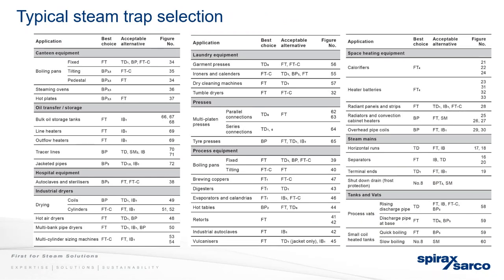There are a few things to consider. Certainly in terms of ball valves, we find that high temperature is something that does affect them. So if you are going to use a ball valve, just make sure that it can actually handle the temperatures, especially the upstream valve. If it's 10 bar steam, that ball valve should be able to handle 184 degrees Celsius. Those often become quite expensive.